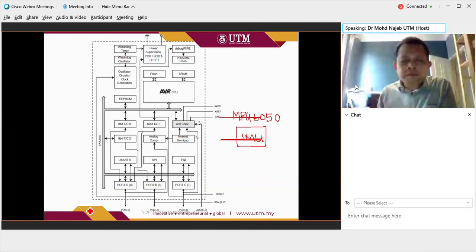If you want to connect two microprocessor boards in the range of 50 to 100 meters, you can use UART. It will be more stable. So SPI is only for onboard serial communication.